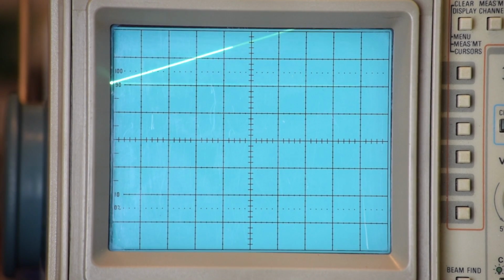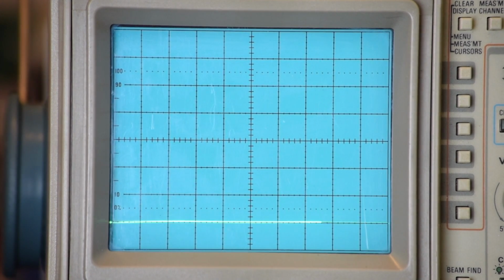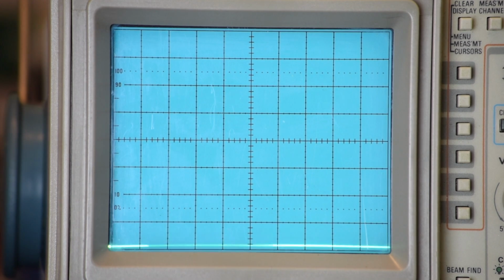As you see here, I'm already in the overload range, so I would need to bring the slope down to get an accurate output from the analog computer. But we have a full range of control on either parameter. I can go with a negative slope, a zero slope, and then the y-intercept can be adjusted to any point within the -10 to +10 volt range.